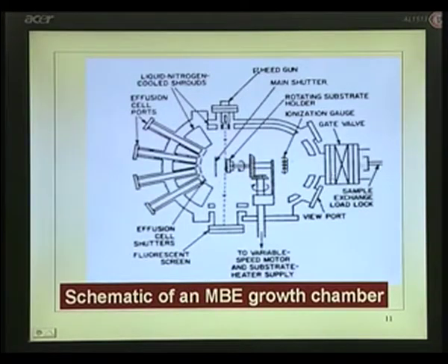And when this vacuum comes down to an acceptable level, if it is 10 to the minus 10, you may have to go close to that here. Then open this gate, push the sample inside. Okay. And here also you do not push the sample straight away into the process chamber. There will be another chamber in between in the most modern systems, which is a preparation chamber. So, one is for loading it, so that you do not open the chamber to atmosphere. The other one is the preparation chamber.